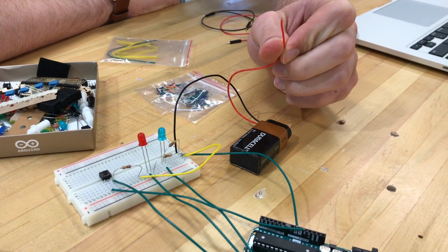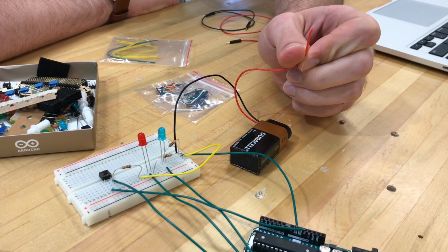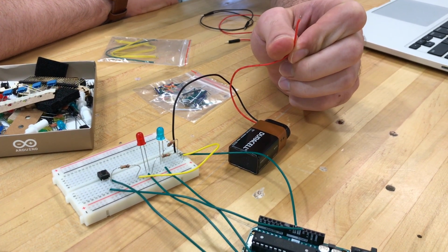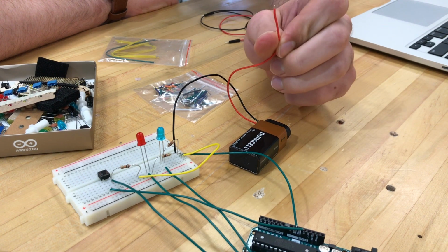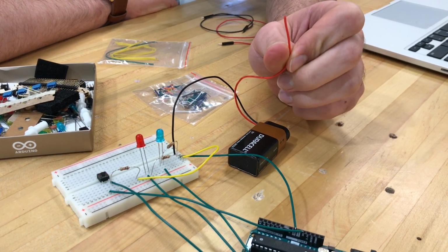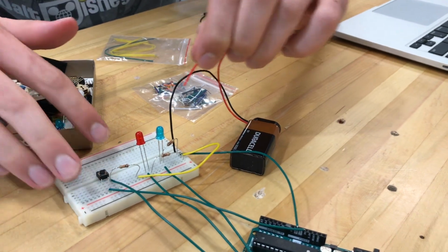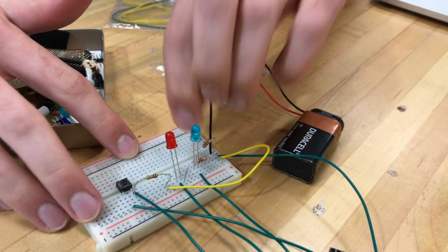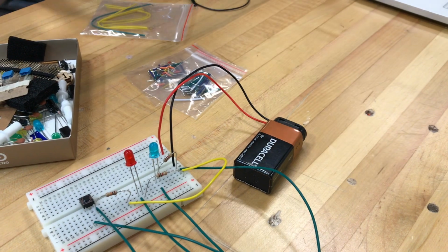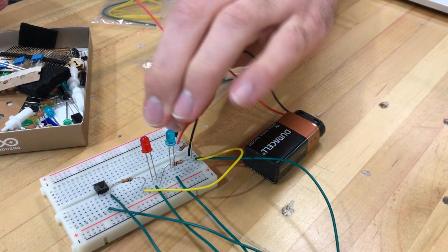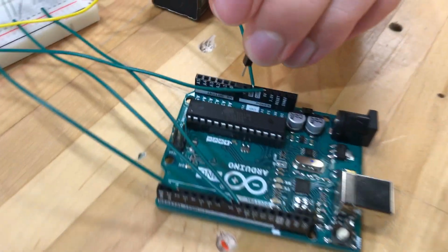This pin is designed to take power from a power supply and convert it to the 5 volts that the Arduino needs. Once again, we can't plug this wire directly into the VIN plug because it's too short, but we can put it on our breadboard and then run an external wire, such as this one, from our breadboard over to the VIN port on the Arduino.